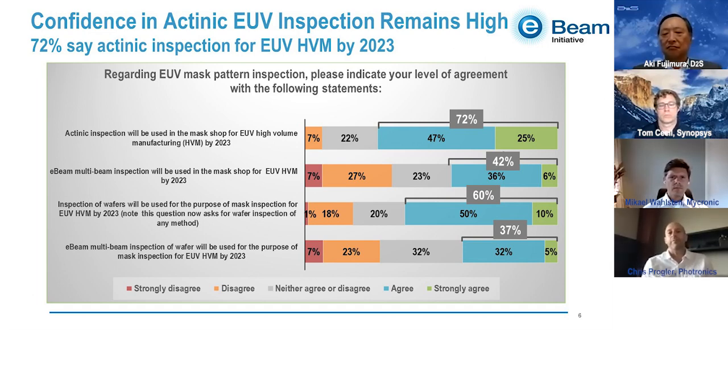Then in the wafer fabs, I think for sure they need to inspect wafers at very high resolution and high speed. Multi-beam inspection for the wafer fabs makes a lot of sense. In that case, it's more of a statistical sort of inspection step, unlike mask making. So I think that's where that fits in. Wafer high-speed inspection married to wafer prints will do what's clearly going to be a higher rate of mask validation in the fab for at least the next 3 or 4 years for EUV. That's where that piece of the inspection infrastructure fits in.